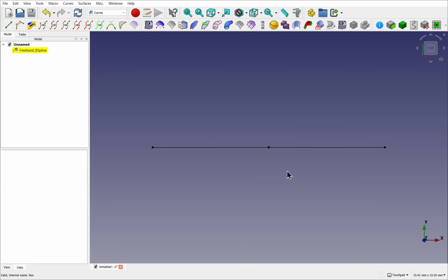This is an actual B-spline. I can manipulate these points by hovering over them so they're pre-selected and clicking the mouse to highlight in green and dragging the point out. You'll notice that by the size of the point, we get 2 blue lines. If I drop that point, you see that the blue line connects the point we've dragged and the opposite point together. This is known as a segment line.